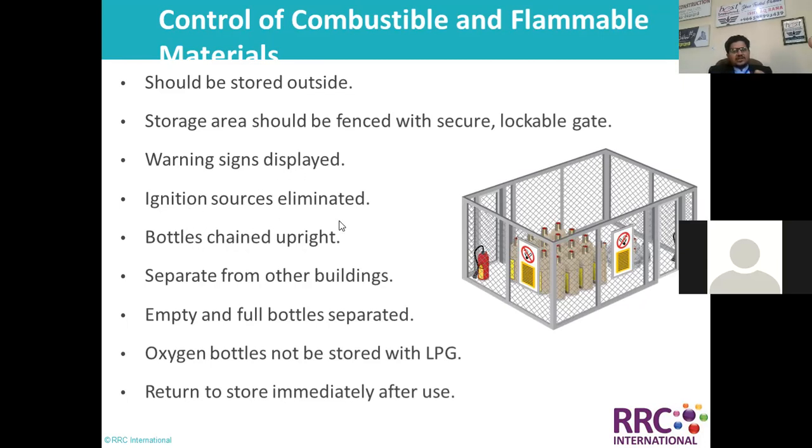No ignition sources. Bottles should be chained upright and kept separate from other buildings. Empty and full bottles should be separate; they shouldn't be stored all together. Oxygen bottles are not to be stored with LPG, and should be returned to store immediately after use.